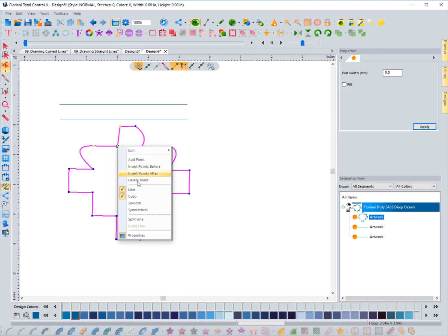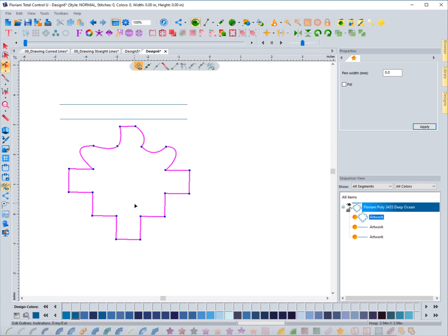So let's right click on it again and instead choose smooth. So when I choose smooth, it's important to understand how smooth works. With smooth, it's different from symmetrical because if I click and drag one handlebar, notice that I can make this handlebar really long and I can move it around. But notice that the handlebar on the other side, meaning this one right here, doesn't change. It stays exactly the same. It might move around, but the distance keeps identical. That's important to know about a smooth node or point.